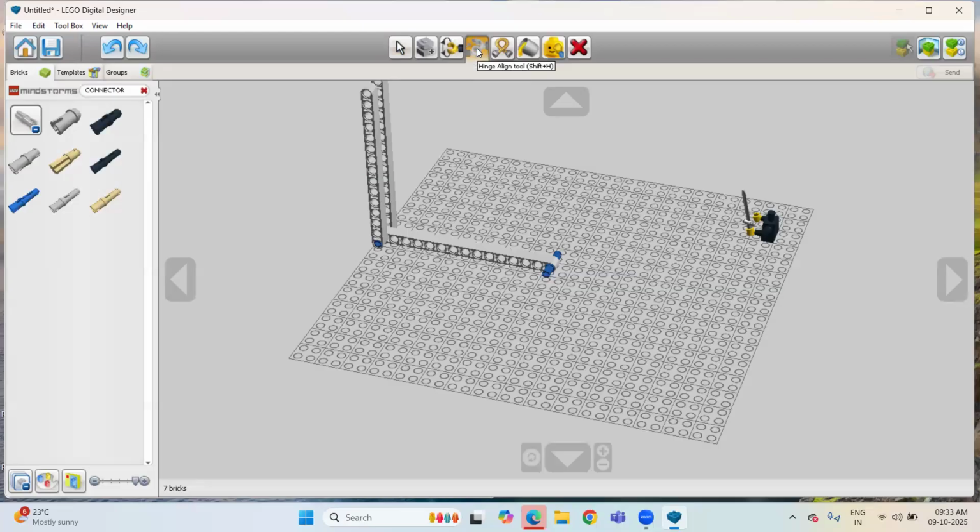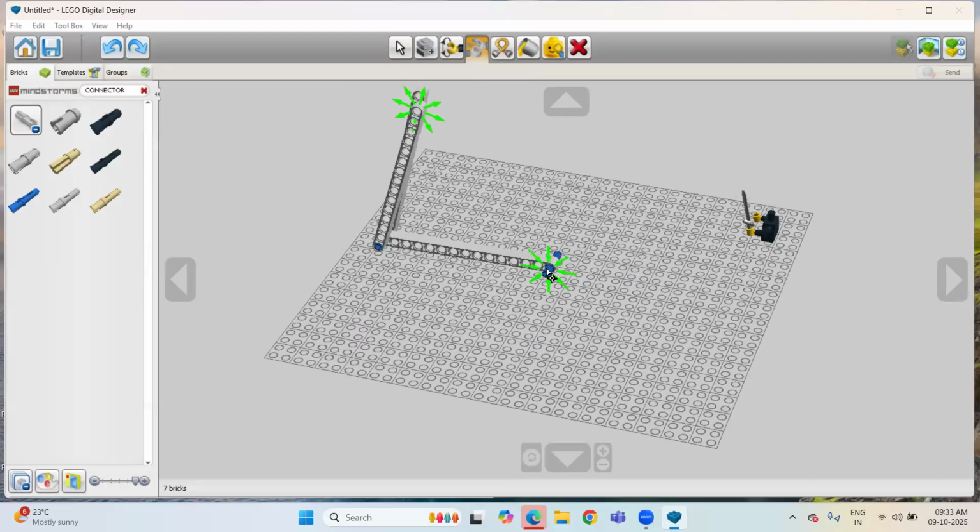And then click on the first hinge part, from where you want to hinge and rotate, and then click on the second hinge part that should match it, where you want to match it. Like this is my first position from where I want to give connectivity, and where I want to assemble, here. This is the second part, the second area of the hinge. So I will click on that to match it, right?